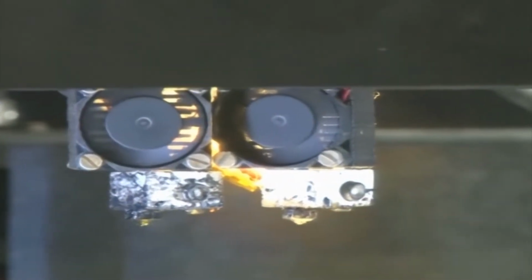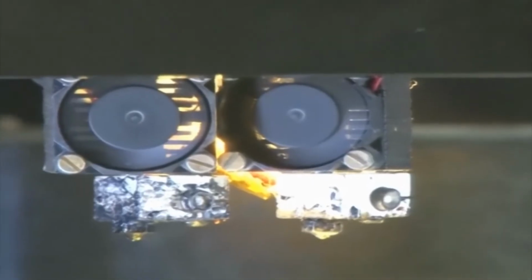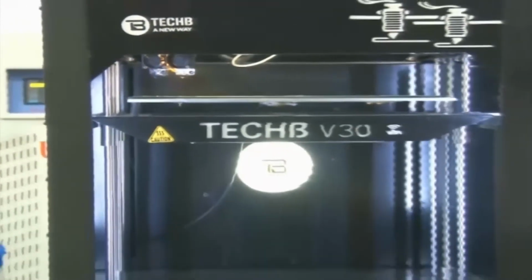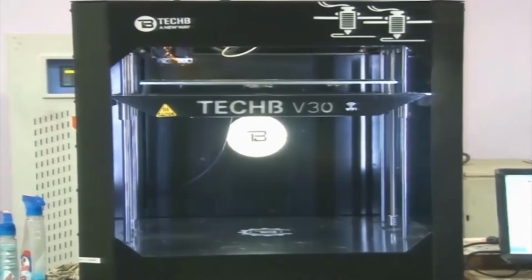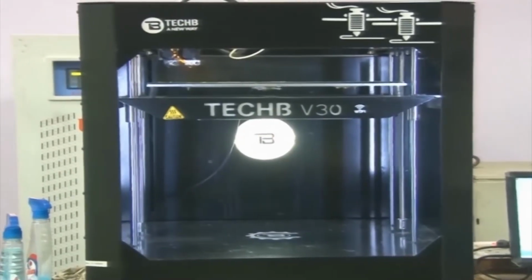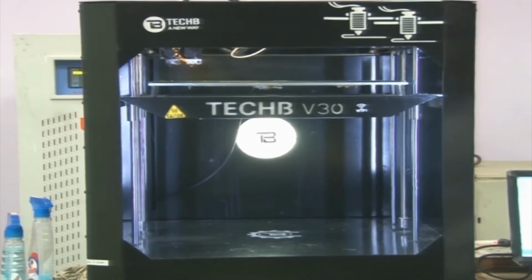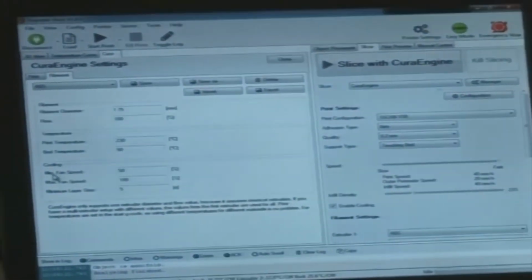This is one more thing that we mentioned earlier, there are two fans, fan 1 and fan 2 here. After it fuses, it becomes viscous, and for a long time it will de-shape the CAD model if it is not properly controlled with respect to temperature. So, after depositing, these fans are responsible for the cooling and solidification of the layers. That is why it is mentioned in the software as cooling.